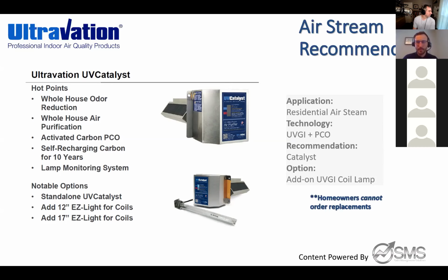So if you have two air handlers, you would only put it in one, or would you put them in both? If you have two different air handlers with two different supply ducts, you have to do two different supply applications. Yeah, correct, that's a great point. Unless both air handlers are pushing the air back into the same supply? I've never seen that, so no, you have two. That's a great question, actually, Ron.